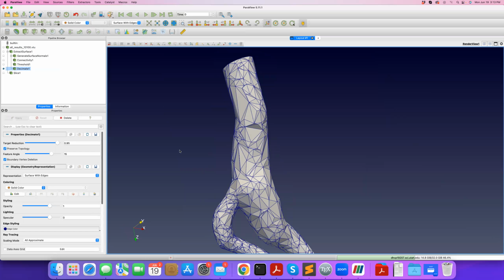Then let's see what else we want to talk about today. If you continue along filters, another nice feature is, well, there are many features here. I'm skipping most of them. I'm just talking about the most useful basic ones. Mesh quality is another interesting thing: you can get some metrics of mesh quality if you apply it, and then visualize those metrics on your mesh.